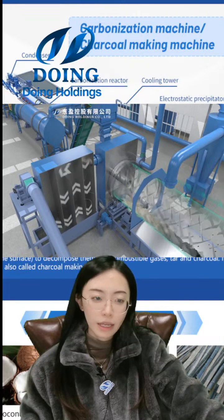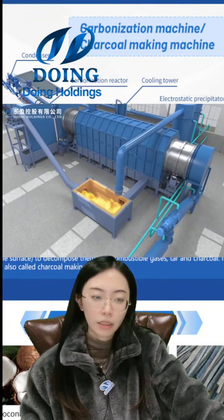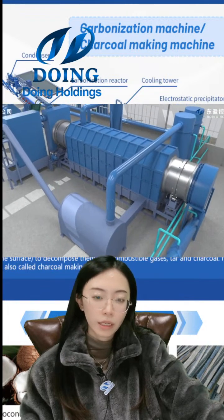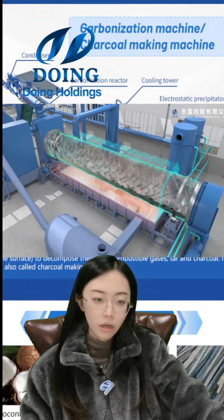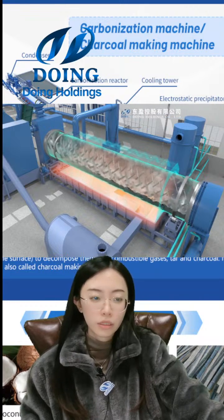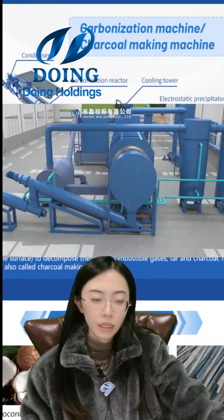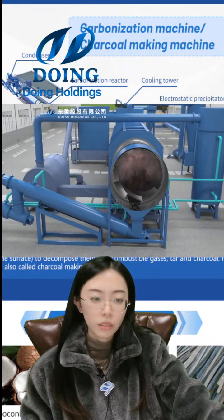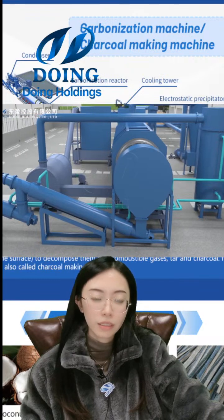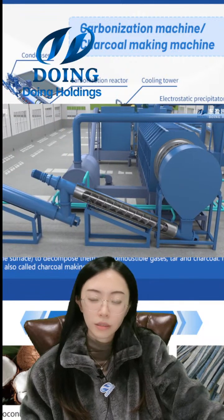In the carbonization stage, the biomass takes nearly 30 minutes to get the charcoal, under a without oxygen or low oxygen environment. The post-treatment stage is to separate, purify and process the char products in order to obtain the carbon products to meet the requirements.